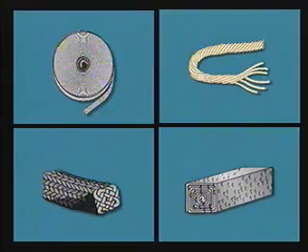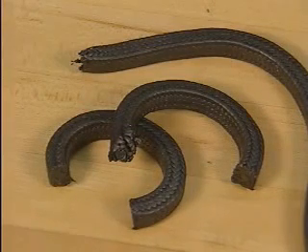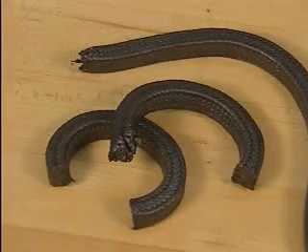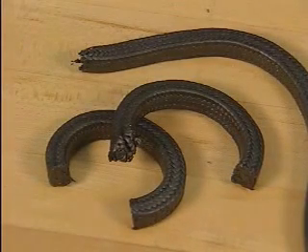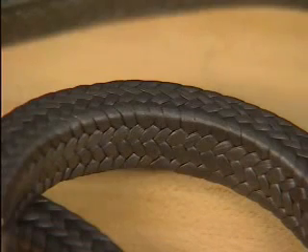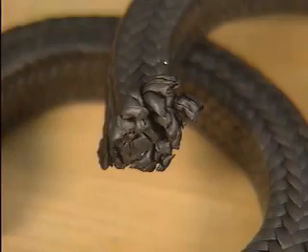Many packing types fall into a common category known as compression packing. Compression packing generally consists of several elements that include a mix of fibers, a binder material, and a lubricant. The fibers can be natural or synthetic, and they're usually twisted, braided, or woven. Binder materials such as grease or wax help to hold the fibers together.